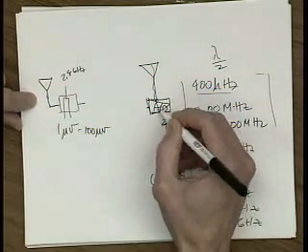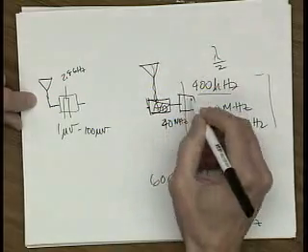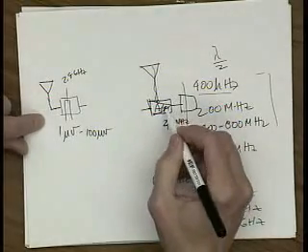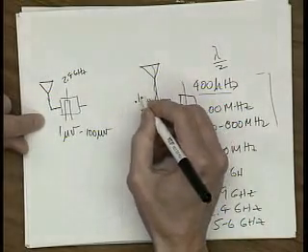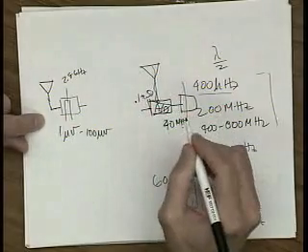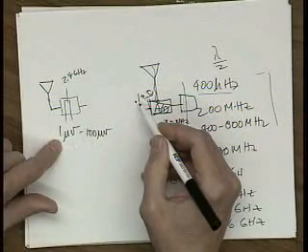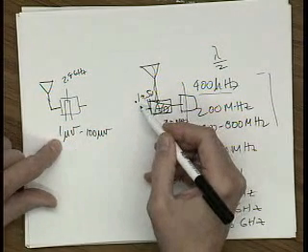This is the sampling rate of the A to D converter I talked about last lecture, and then it goes into the digital processing afterwards. It needs an input signal of probably a tenth of a volt up to half a volt. So we have something that's a microvolt, and it needs to get up to 100 millivolts. So we need a gain of like what?